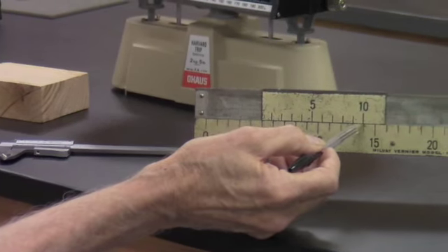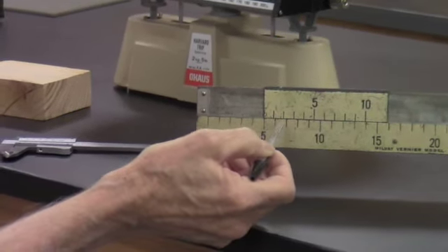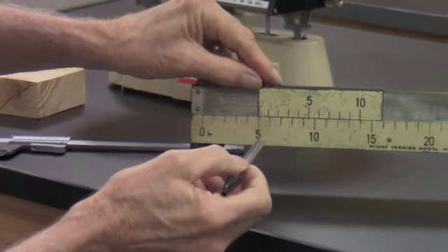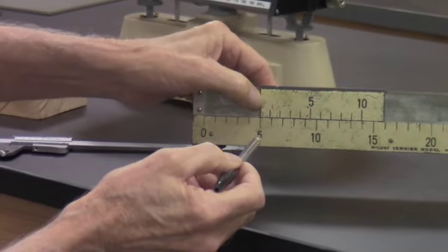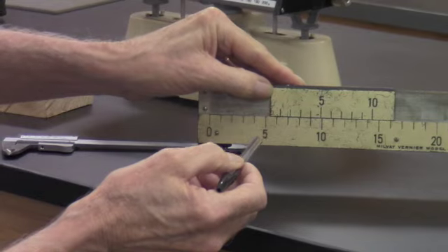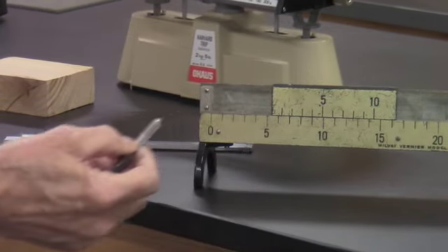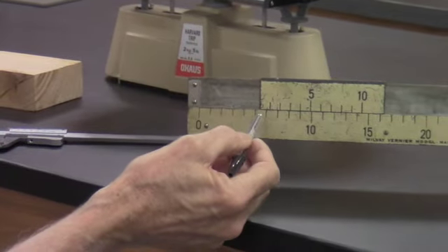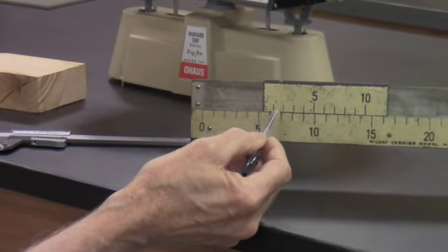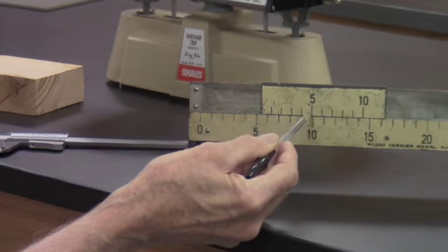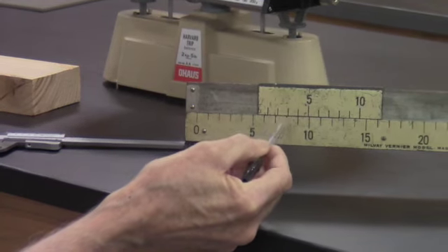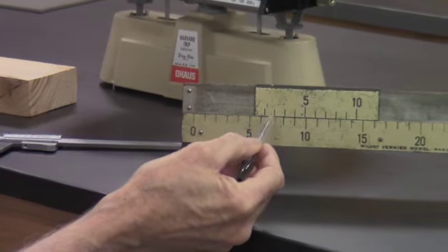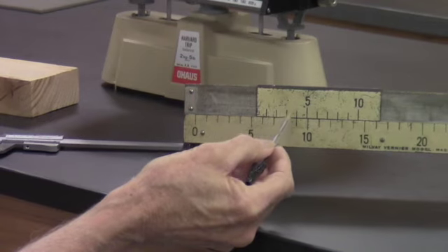And the line that lines up best over here is the 10 mark. Each one of these lines, you notice, let me move this over halfway. Okay, so this is going to be 5.5 centimeters, as I would read a meter stick, for instance. But because each of these spacings is 10% smaller than these spacings down here, the next spacing is going to be closer to the mark below it and closer and closer.